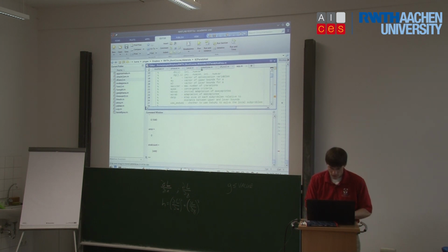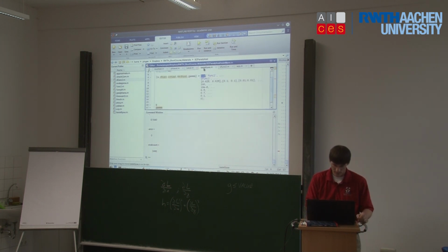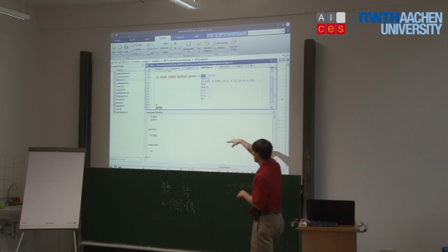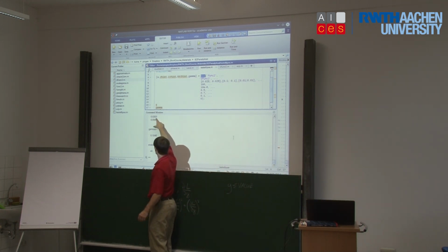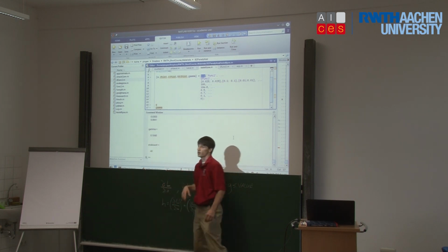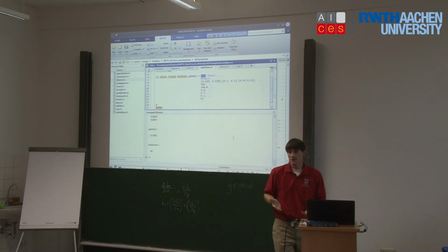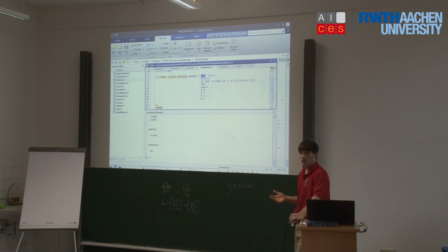And when we then run this test ellipse program, we evaluate it, and we get exactly this. Now we actually did it in 2 dimensions, so we solved for both A and B. We got the same gamma value, so same A, same B, same gamma value, and the total evaluation count of L was only 40. So instead of solving L, our CFD problem, 2,540 times, or however many times it was, now we're down to just solving it 40 times, which is much better than